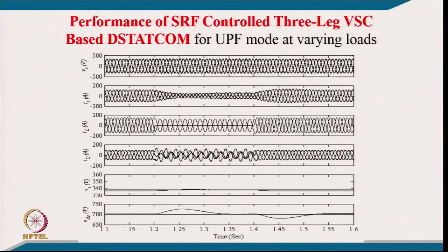So, the compensator has to generate unbalanced current, so that the grid currents are balanced, and again when the load is put back it comes back. And you can see here we are not regulating the voltage at the point of common coupling. So, when you have a load, certainly the voltage at the point of coupling reduces from the supply voltage, and when you remove the load it comes closer to that, but still with some small difference.